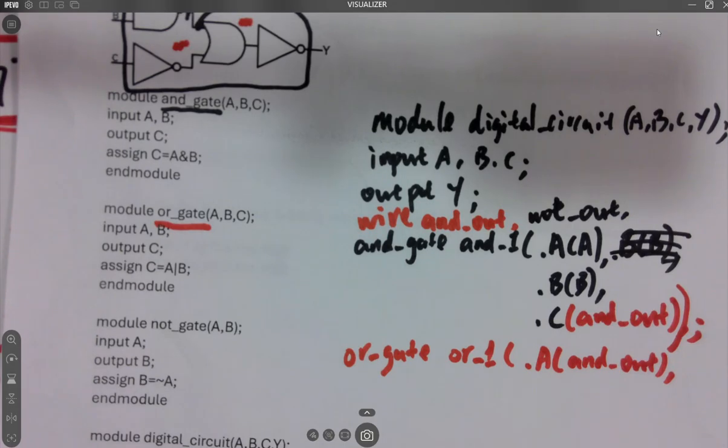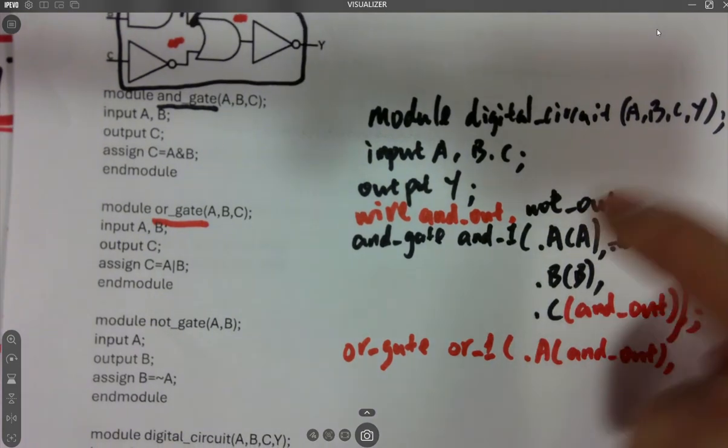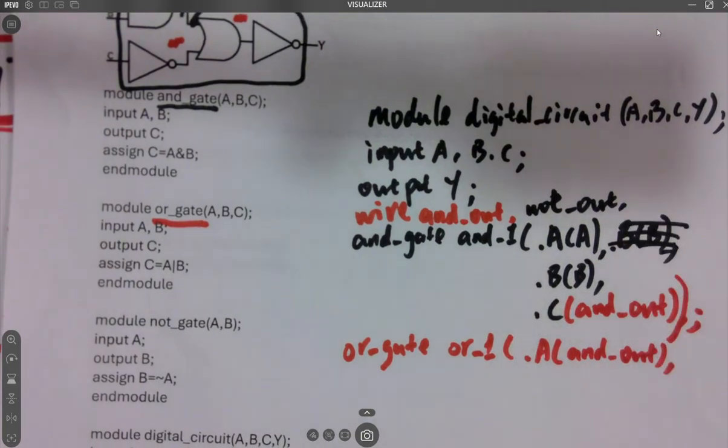Because this is hardware, it's going to be synthesized. It can be a mess if you want. It can just be random order, and it'll still do it, in terms of the gates. For the always block, for the behavioral, sometimes it does matter, but in most cases like a combinational block, definitely not. It's just like a snapshot. It's done. It's a piece of hardwire.